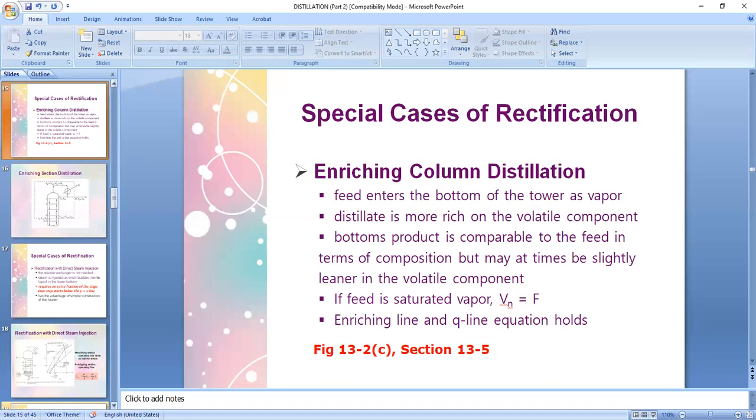Actually, originally, it's the liquid that goes down into the column, and your reboiler turns it into vapor and returns it back into the column. Majority, however, of this collected liquid is withdrawn as the bottoms liquid. So in this scenario, since your feed is vapor, we look at it just like that vapor coming from the reboiler, and it's represented by V sub N.